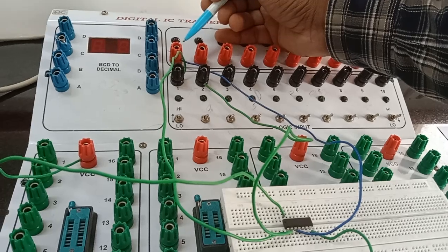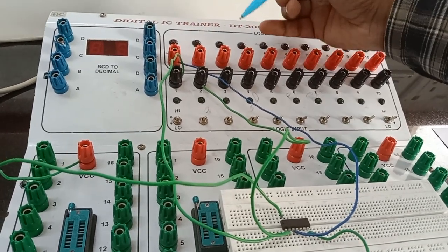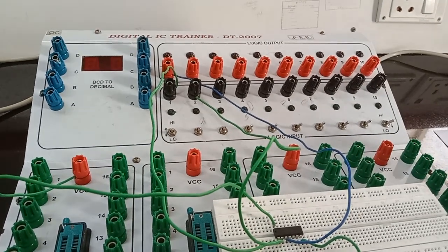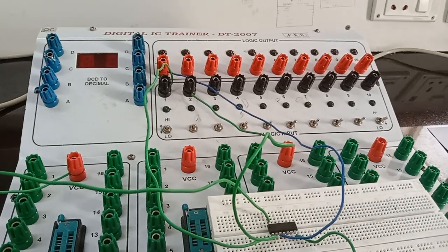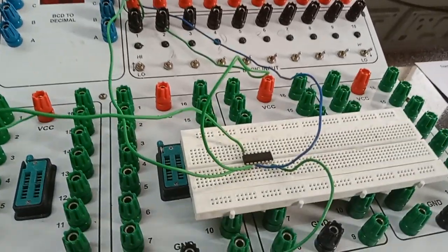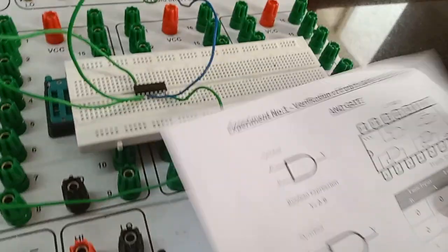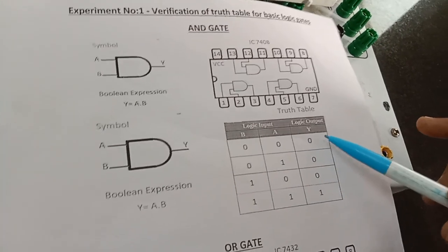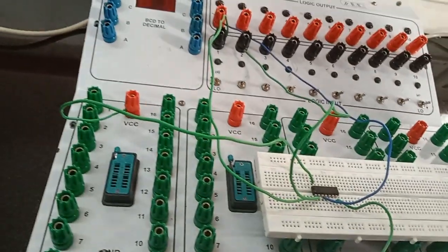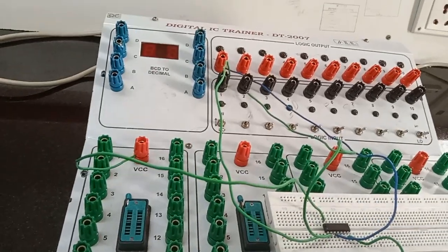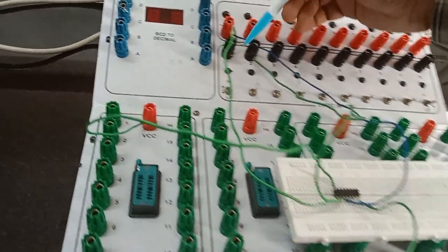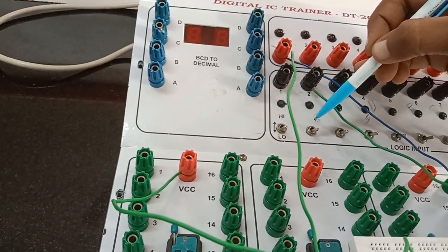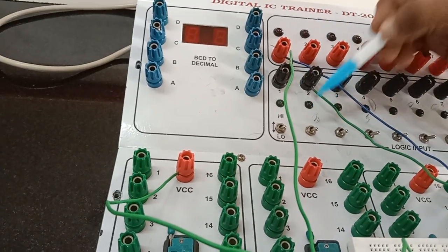Input value 0 means low value, input value high means 1. So we are going to do the binary multiplication for the two inputs with the help of this AND gate. I am going to verify this truth table. So here, we are giving the input 0 0, means output equal to 0. I am giving the power supply and the trainer kit is switched on. So supply is going to the circuit. Two inputs are 0 0. For example, this is input A, this is B. Both inputs are at low value, that is 0 0. So output is also 0.